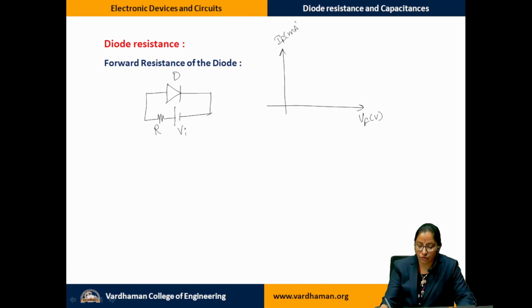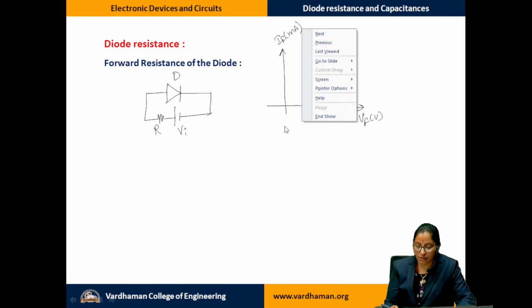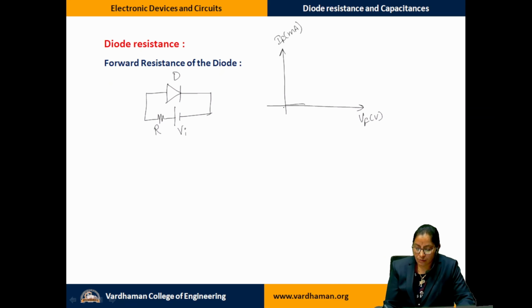which will be in the range of milliamperes as we have analyzed in the last class. We have the characteristics in this manner, almost a zero current till a V gamma potential. Once the barrier becomes zero, we see that at V gamma the conduction gets started. That is, majority carriers start moving from the junction. So respectively we are going to have the majority carrier current constituted.